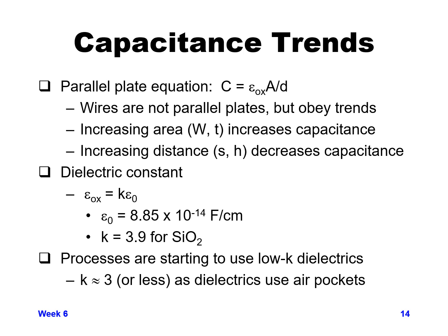Increasing area can be done by increasing the width of the wire, which you do control for a given process technology, or increasing the thickness of the wire, which you don't control. Once you choose a given process technology and a given wire thickness for a given layer, if you make the wire thicker, it will have more capacitance to its neighbor next to it. It won't have more capacitance to the layer above it or below it, but more capacitance to its neighbor.